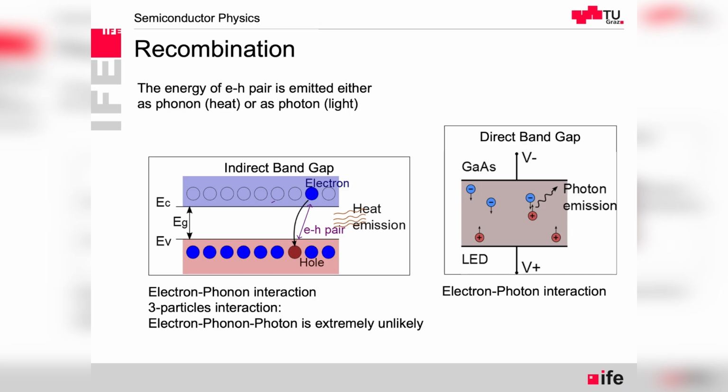And that's why gallium arsenide is a material that is known for photodiodes, because with recombination, we have emission of a photon. So that would be the important conclusion, also going step-by-step through the EK diagrams to get to the point that we have those two different types of semiconductor with indirect and direct band gap. And also the important dependencies on the planes of the crystal that we work with.